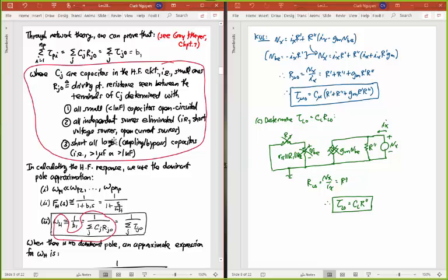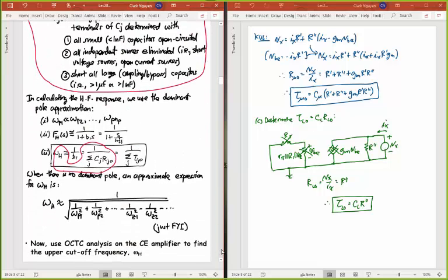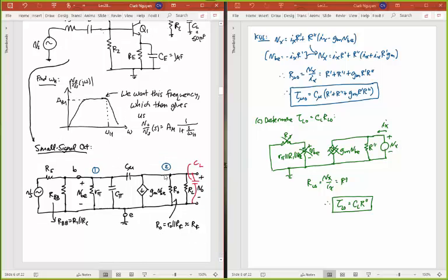But just in the end, it makes sense that you open circuit those capacitors because you're really handling one capacitor at a time. So if I'm looking at this circuit, I've got 3 capacitors in here. And so if I want to handle one capacitor, we just handled CL, and I want to get its driving point resistance, I can't have these capacitors around because they'll have another driving point resistance associated with them. So to get the driving point resistance with CL, which is all the resistance in parallel with CL, I need to eliminate these capacitors, and to eliminate capacitors, you open circuit them. Okay, I don't know if that explanation helps with that, but that's pretty much what we're doing for this here.